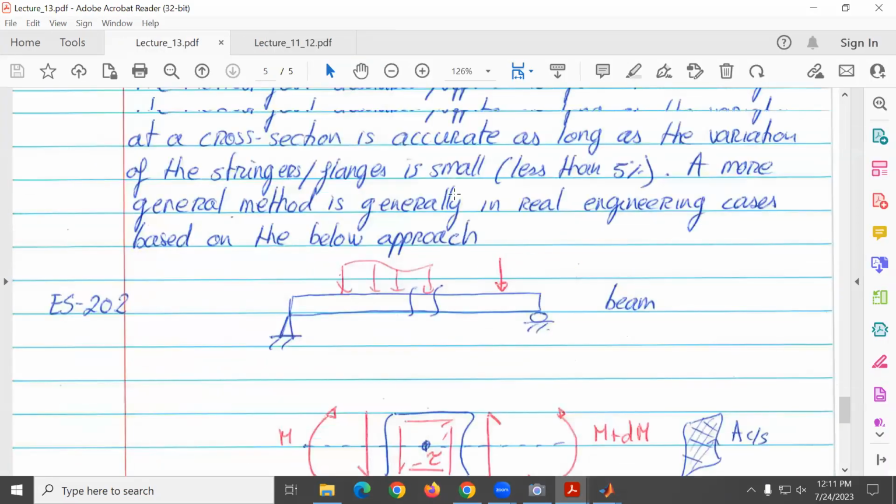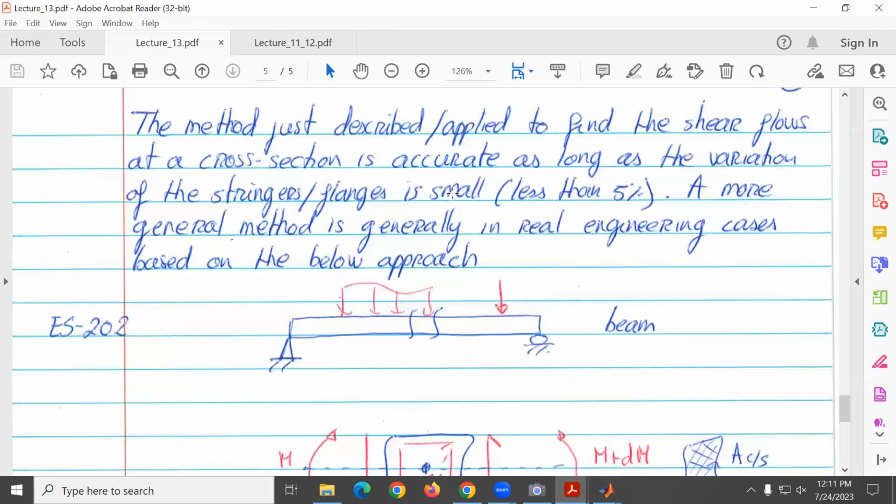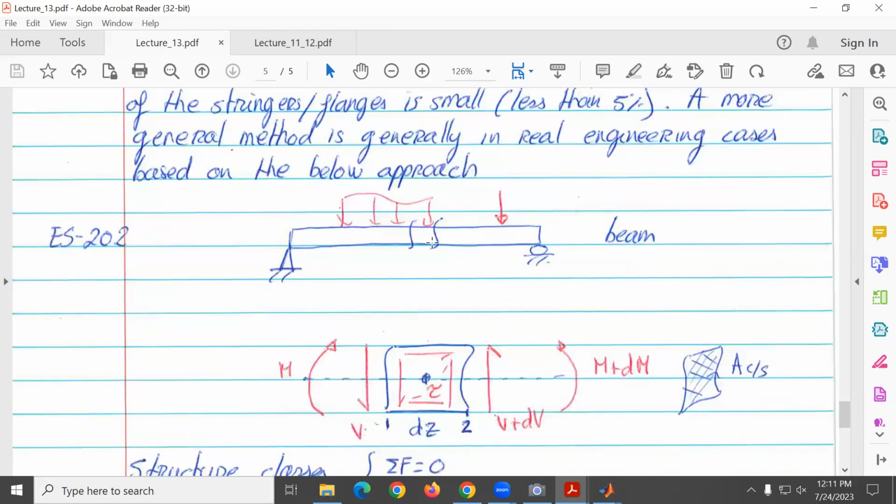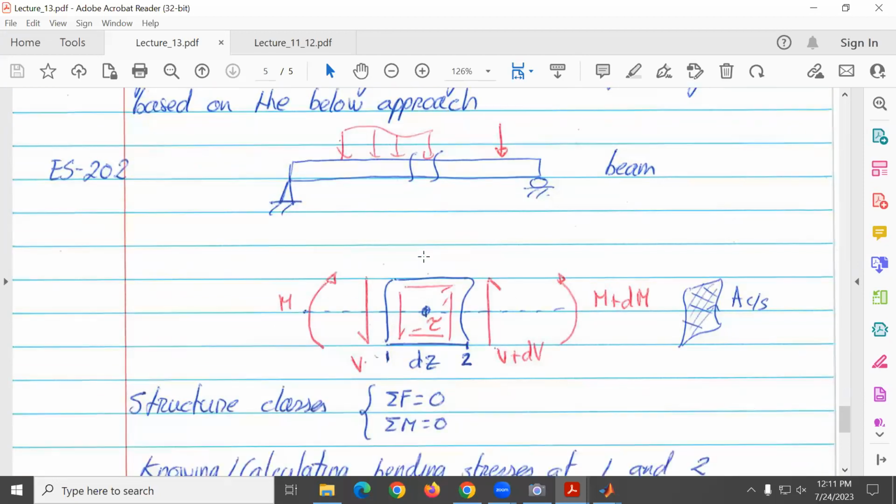I cannot derive something that probably you derived in solid mechanics, that if you have any type of beam structure subjected to a loading, and you take one element, you make cuts so that the internal actions become external, no? When they become external, then you can use summation of forces equal to 0 and summation of moments. But this will have a shear force here, and then a different shear force on the other side, referred to as V plus dV.